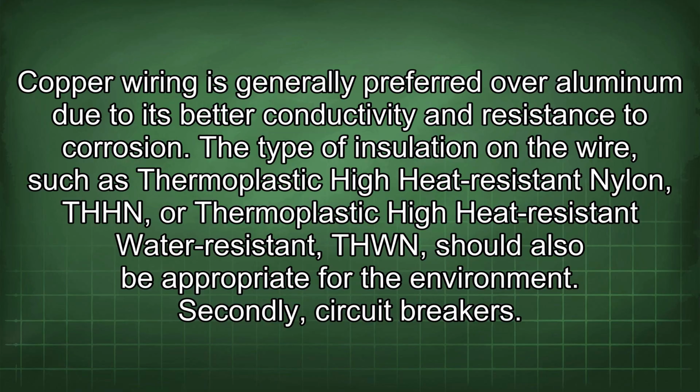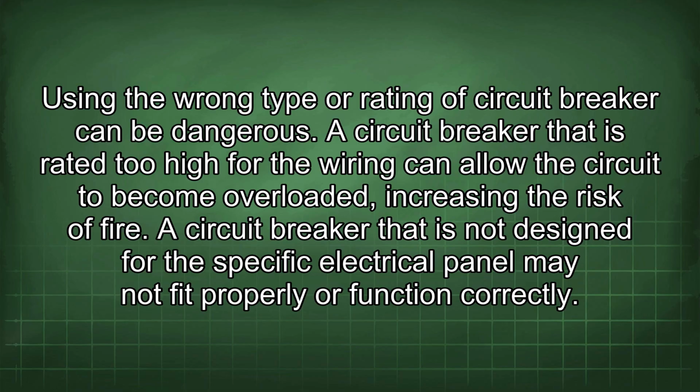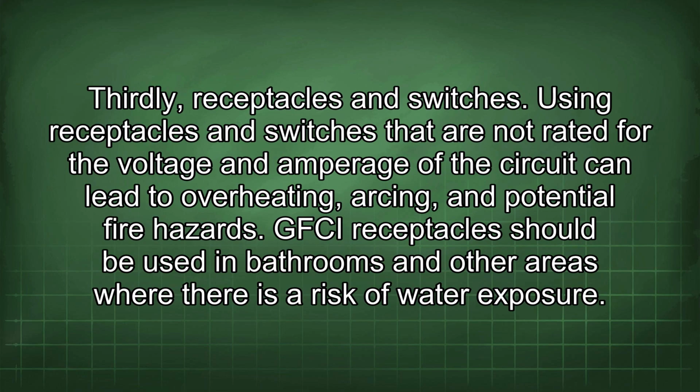Secondly, circuit breakers. Using the wrong type or rating of circuit breaker can be dangerous. A circuit breaker that is rated too high for the wiring can allow the circuit to become overloaded, increasing the risk of fire. A circuit breaker that is not designed for the specific electrical panel may not fit properly or function correctly.